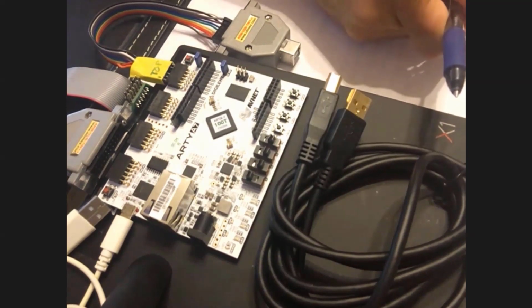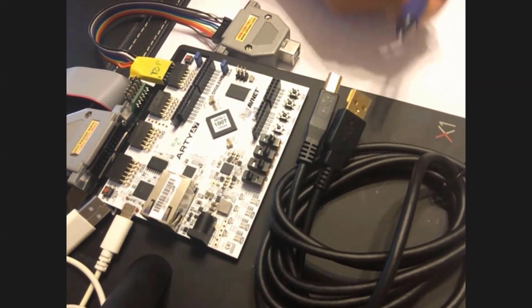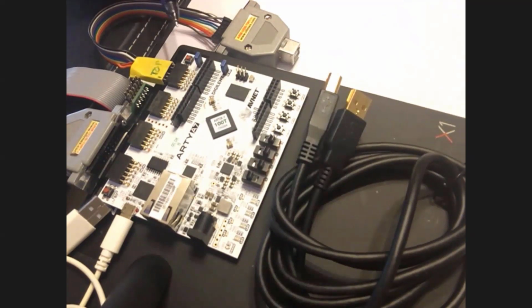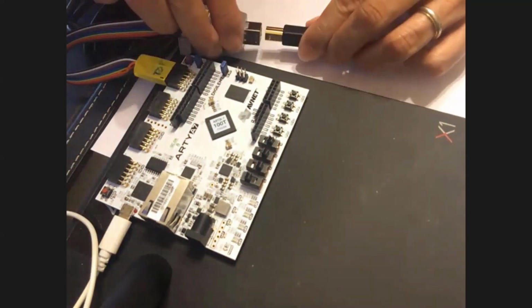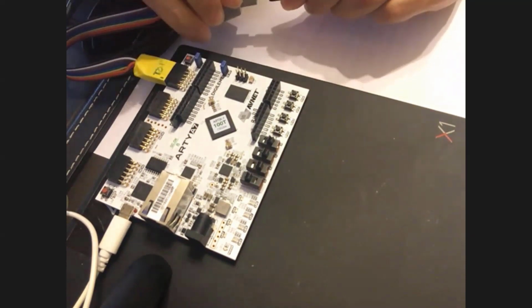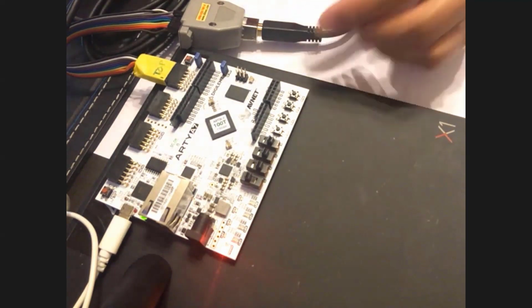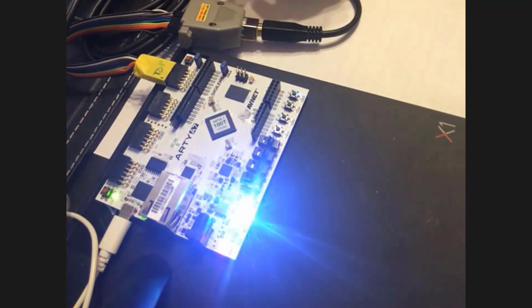The other USB cable, which is a type A to a type B, where the type B will be used to connect to the tiny debugger module. You will also need 10 male to female cables for connecting from the tiny debugger module to the female PMOD here. For SiFive customers, SiFive does provide these male PMOD connectors, as shown here. All right, let's connect this up and power up the board. Okay, as you can see, that's very nice and bright.